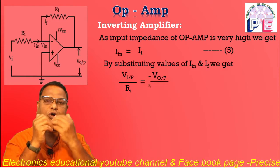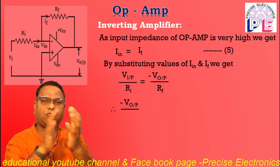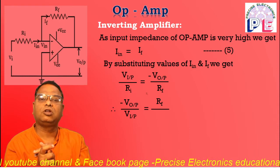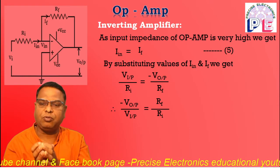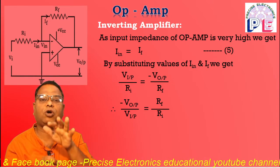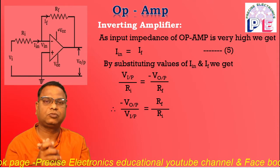Now V output upon V input is equal to RF upon Ri. We brought the voltages to one side and the resistors to the other side. So minus V output upon V input, because V output is minus, is equal to RF upon Ri.